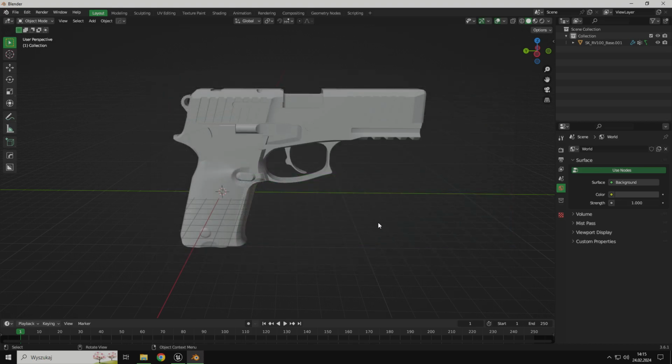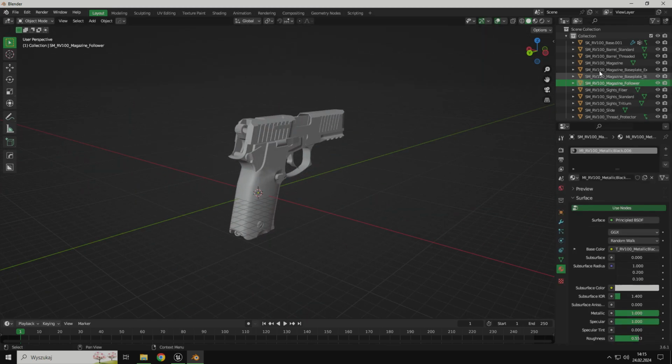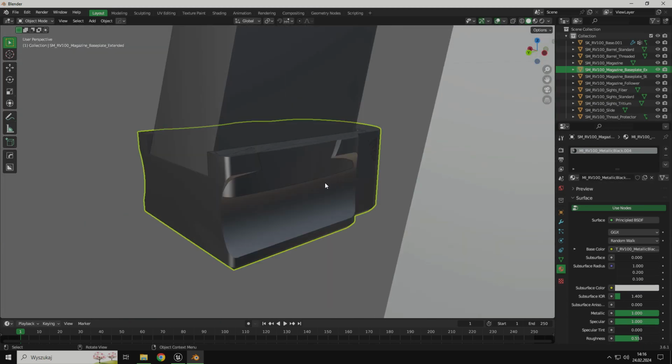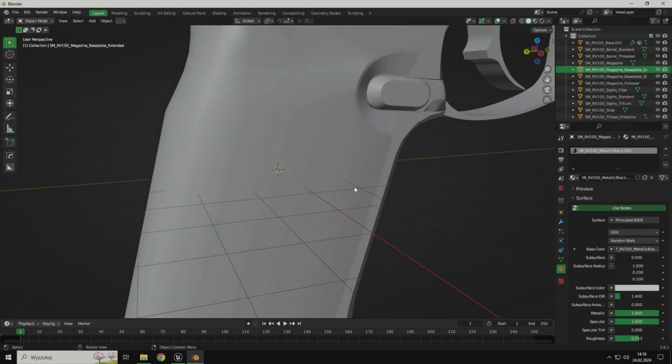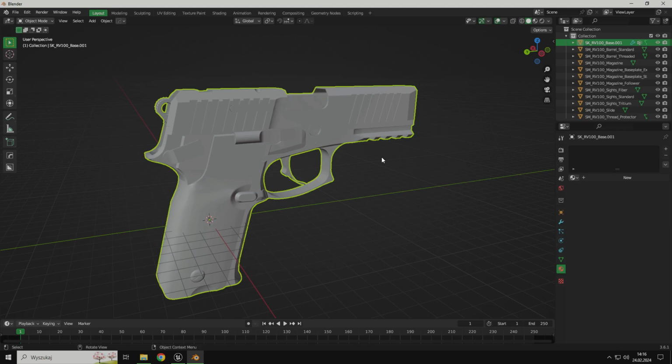It looks like nothing has changed, but if you look at the Collection panel, we have added new objects to the scene. They are invisible because they are much smaller than our skeletal mesh. If you select one of the new objects and focus the camera on it, you will see that it sits inside the skeletal mesh. We need to match the scale of our skeletal mesh with our static meshes.